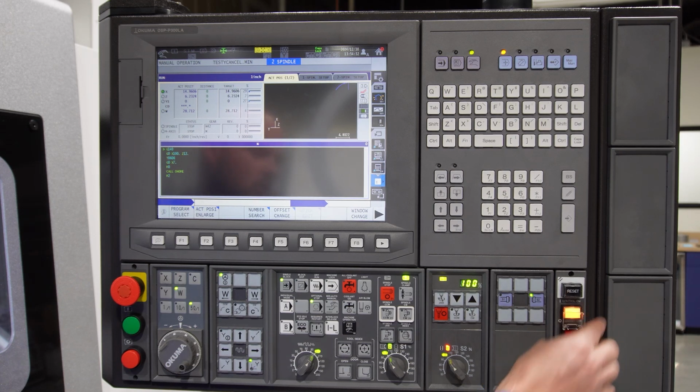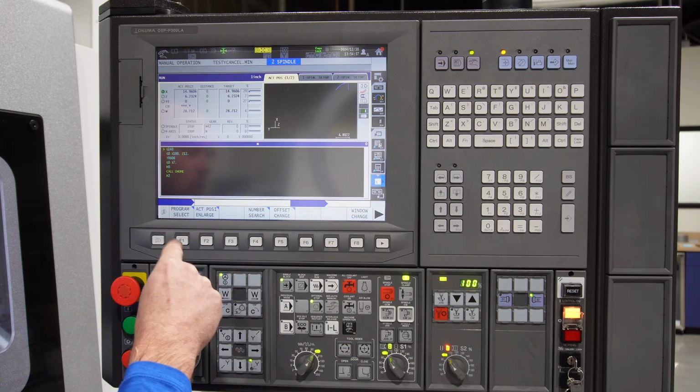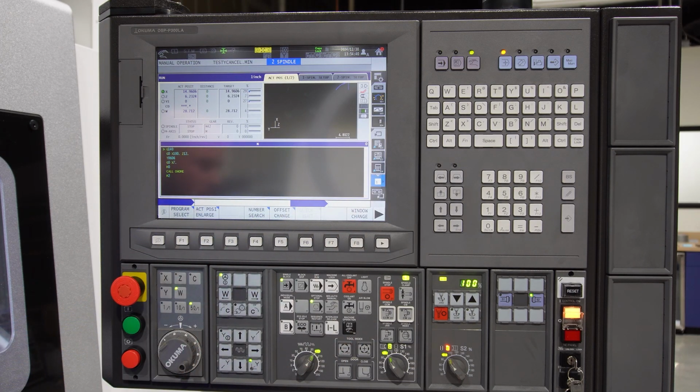Below that is your control off button. You turn this off and this will power down your control before shutting off the main power on the machine. Next, we have an NC panel key. This will lock out functions of the machine based upon where it's set, depending on whether you have setup or operators running the machine. At the bottom here, we have our door interlock key. If this is turned to the off position, it will inhibit all machine movement while the door is open.